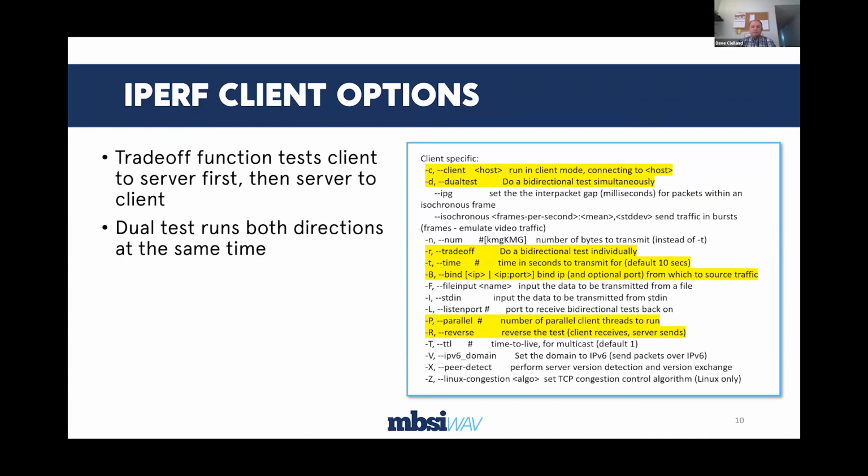So it's an awesome tool to use during acceptance of your base stations, because you can set up a probe running an instance of IPerf, set the test to run for a number of days, and it will run as much data through the equipment as the equipment will support. So it's great from that perspective.